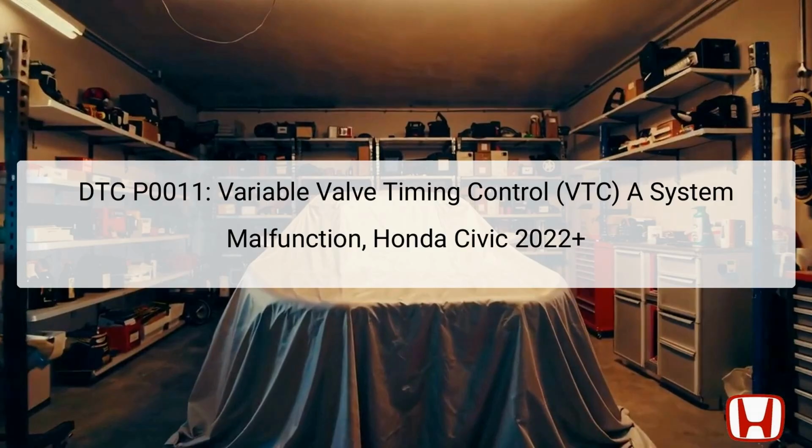The VTC system plays a crucial role in optimizing engine performance by adjusting the timing of the intake valves, thus improving efficiency and emissions. The general location of the VTC components is near the engine's cylinder head, where the camshaft is situated. Understanding this code is crucial for maintaining optimal performance in a Honda Civic 2022 or newer model.